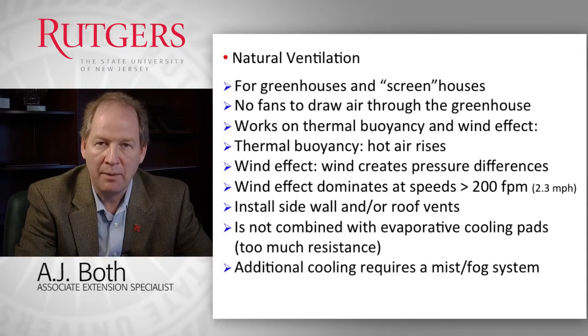Discussing natural ventilation in a little bit more detail, these systems can be used for greenhouses as well as screen houses, so greenhouses that are just covered with a screen, as we see in some tropical or subtropical climates. We don't use fans to draw air through the greenhouse with these systems, but we use two different physical processes to move air. The first one is called the stack effect or thermal buoyancy, and that means that warm air is less dense than colder air and thus rises up. Think about the stack in the chimney in your fireplace at home.